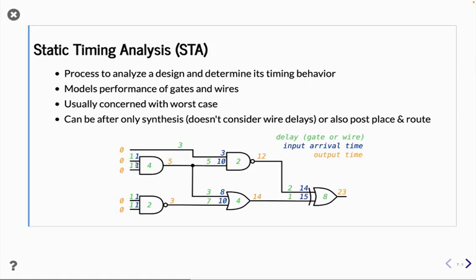Okay, they go through this initial wire delay, and then they arrive wherever they're going. So for example, this has a wire delay of 1, so it arrives here at time 1. Or it has a wire delay of 3, so it arrives here at time 3. Then we add on the gate delay. So for example, over here it's just pretty simple. It comes at time 1, gate delay of 4, time 5.